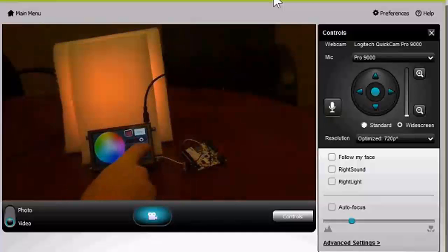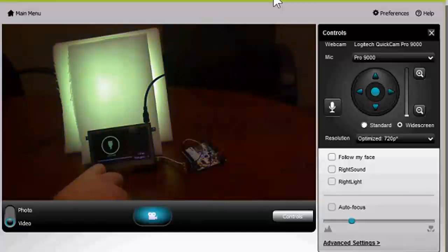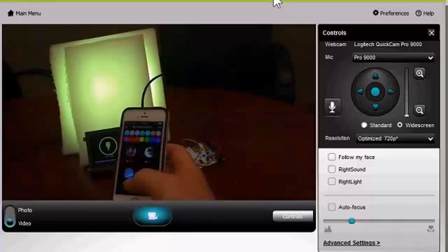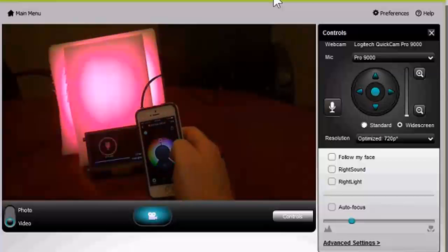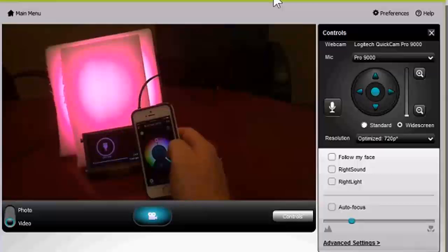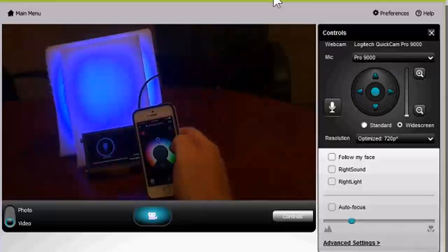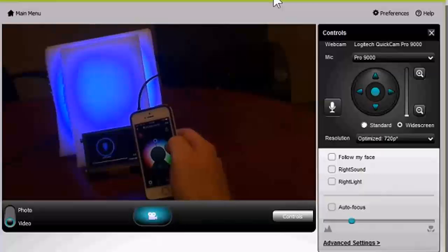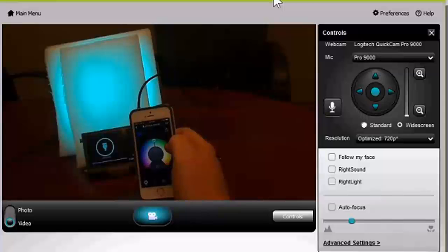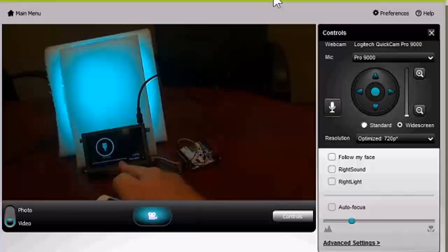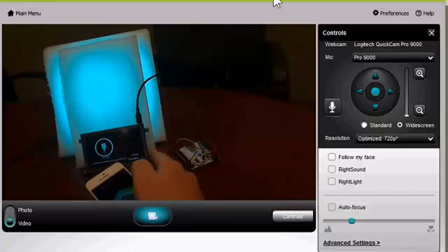I've got sliders here, and we can hit done. And then also, just for funsies, I'm going to bring up the LIFX app, change the color on here, and the color on my Amulet GUI changes automatically. So we're just in a little polling loop here, requesting the data from the bulb directly. My phone here is actually talking to the cloud, and then the cloud is talking to my bulb, and down here the Amulet module is talking to the Wi-Fi chip, which is talking to the bulb directly over our local area network, just a LAN message.